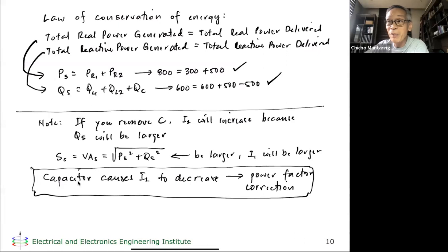So ngayon, pag nakita nyo yung power saving device, alam na nyo, no? Baka capacitor lang yun sa loob. Sa mga poste ng Meralco, pag minsan meron silang linalagay na capacitor. Because if the load is heavily inductive, which is usually the case, most industrial loads are inductive, then it will be helpful to put a capacitor across your load so that your total Q becomes smaller and then the current will become smaller. So that's just some insight for you, no?